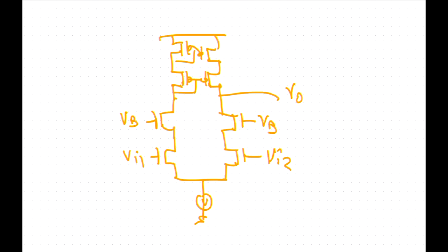You need to make sure that your input range is still really important to have there. But when you do that with a current load, you don't need to have freedom between choosing the output voltage and the input voltage, because it's a voltage follower. So you've got to make sure that it's biased properly, but they follow. So you don't need that extra freedom. That is common to do in these sort of little helping amplifiers.